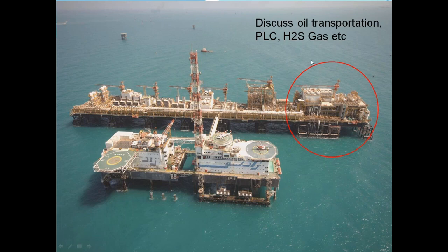And the problem with this, within a minute the person will die. Within a minute. So this is something like a very dangerous alarm. So we maintain all the H2S alarms, we maintain all that equipment, and we'll enter this zone. So the moment the alarm rises, we should stop breathing and we should run from this platform to somewhere to the near side. So that's a dangerous problem here of H2S gas.